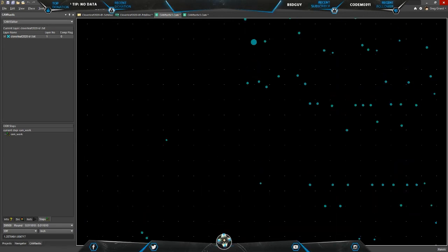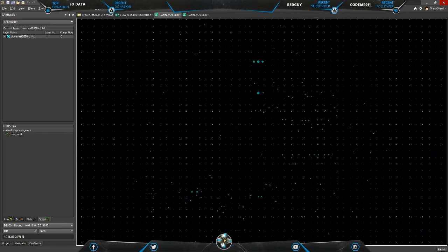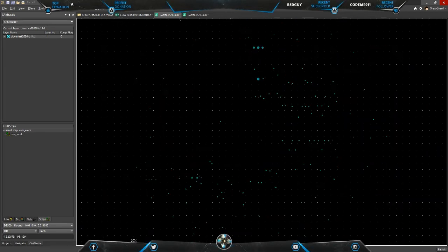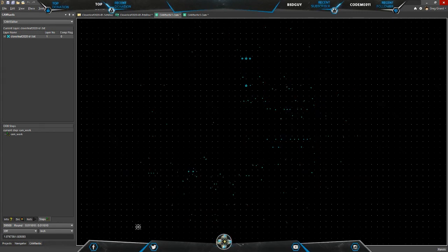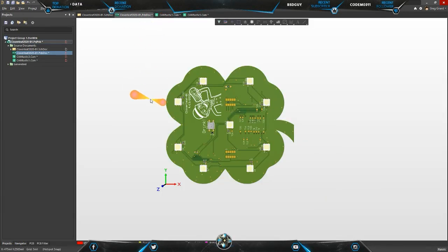And what this tells them is all the drill locations as a file. So when they put this into their drill machine, it knows what bit to use, if they have a tool changer, however they load it, and where the drill should go. Okay. So after that, that's how they manufacture all the circuit board. They have all the drills, they have all the copper laid out.